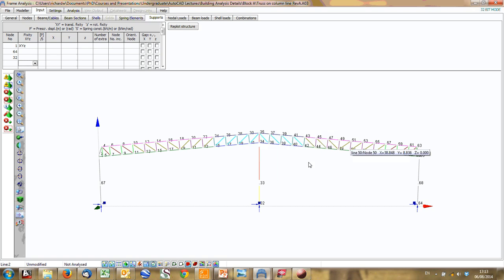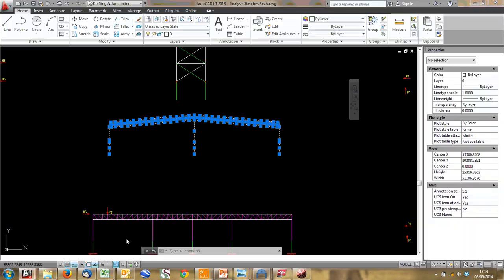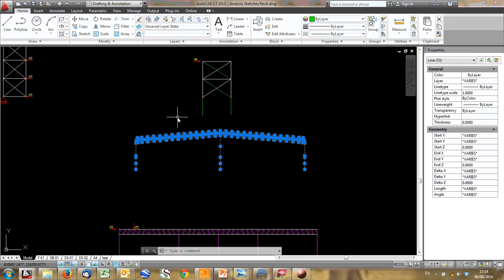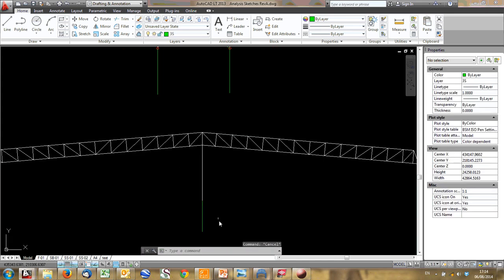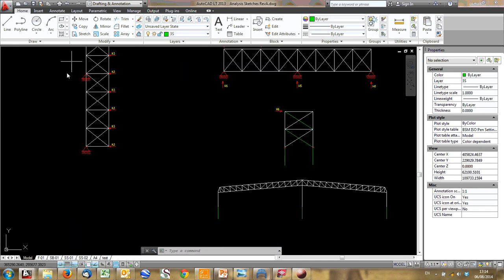where the girder sits. This one is a bit more complicated to analyze because if it's acting as a support, if this bay is much stiffer, it might actually act as a support for your horizontal bracing. So then this load you'd have to apply to this model here. If it's quite slender, then the roof bracing takes it all up. In structures especially, we've got big concrete columns that go all the way up, and you must design it. I'll try to show you an example just now of how you might do that. But then you'd have to apply all the reaction load here to this one and then design that for it.